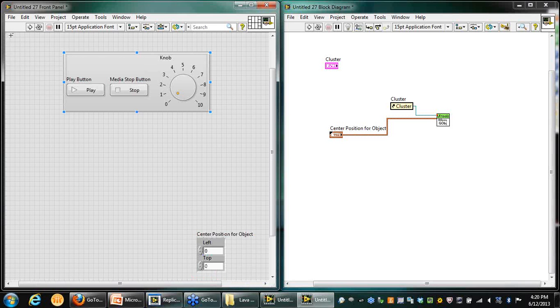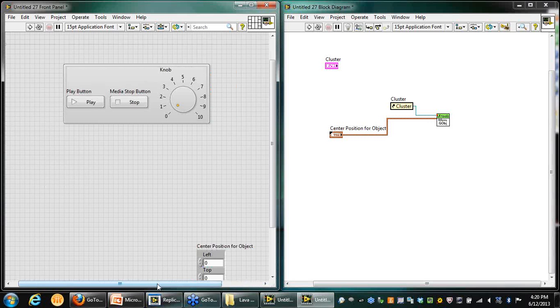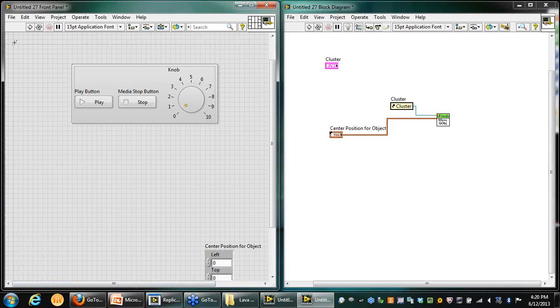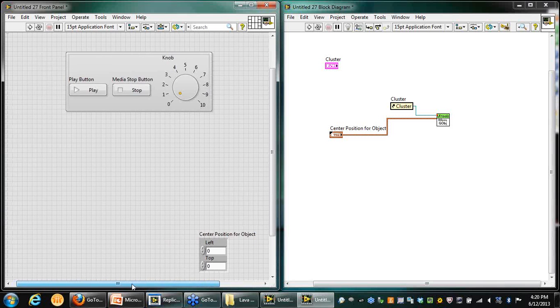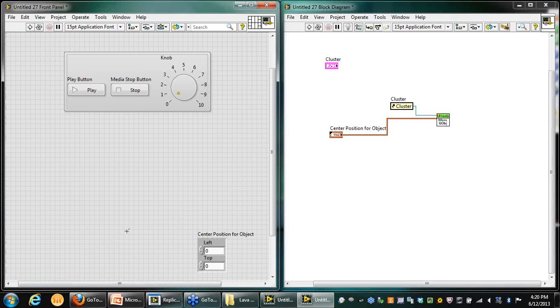So the desired position is with respect to the origin that you see on your top left. Just to zoom into it, every VI that you create has this small thickened part, a dot kind of thing, which represents the origin of any VI. So all these coordinates are with respect to the origin. So I have the origin here, and I give a temporary location, something like 300 from left, and let us say some 60 from top.